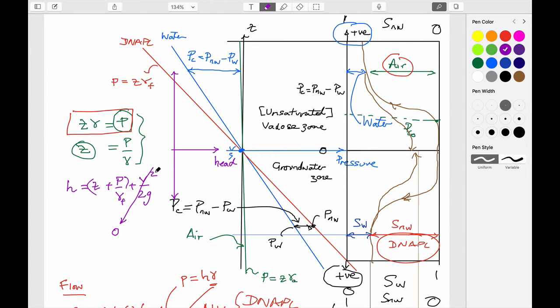And so what happens then if we go up within this fluid and look at how fluid pressures change? If we look at this location here, and if we choose, as we have done, the datum to be 0 here, then by definition the pressure here is 0, the elevation is 0, so if we plot head, the magnitude of head should also be 0. Okay? This is positive, and for Z this is negative. I guess I didn't say that before, but that's true for here as well, right? This is positive, and this is negative.